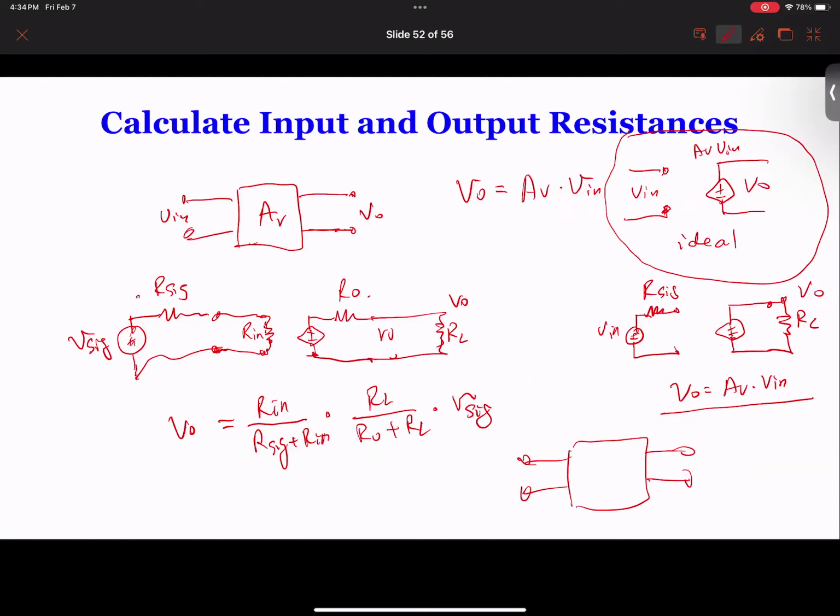So how do you look for input resistance, output resistance, Thevenin's voltage, things like that? When we look for input resistance, we short the output, and then we look at all the resistance. We do parallel and series connections, and we get the resistance. When we look for the output resistance, we short the input, and then we look at what's inside, and look for the total resistance.